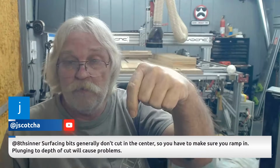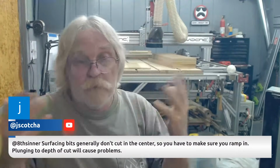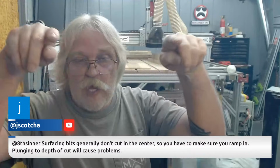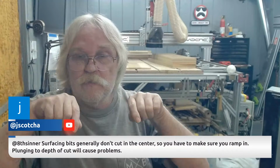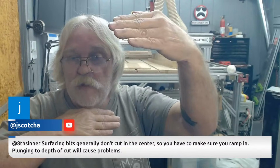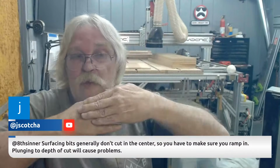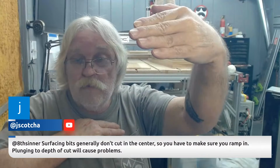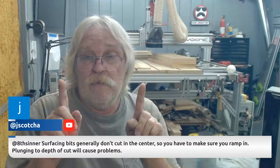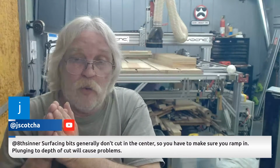So with that 2-inch bit, I'm the guy that makes the rectangle slightly bigger than the piece of material. With this bit, I make it 5 inches longer and 1/2 inch wider. So I know that bit's going to go off the side of the material by 1/4 of an inch.